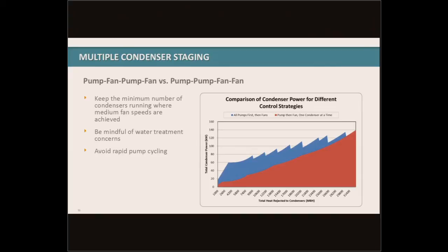A couple things you want to keep in mind, though, are the water treatment concerns. If you get into a situation where your pumps are cycling, turning on and off, there could be some negative consequences with the water treatment and building up scale on the condensers. So that's just something to be mindful of and keep an eye on. You also don't want to be rapidly starting and stopping pumps, because of course that's not going to be good for the motors.